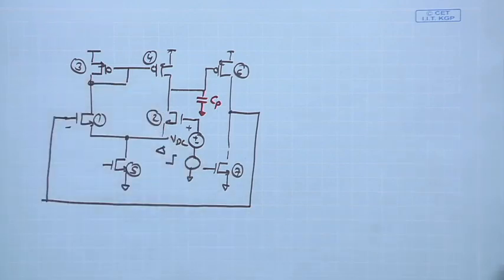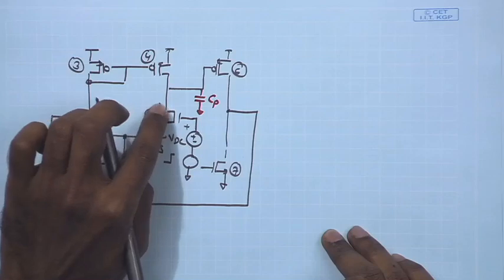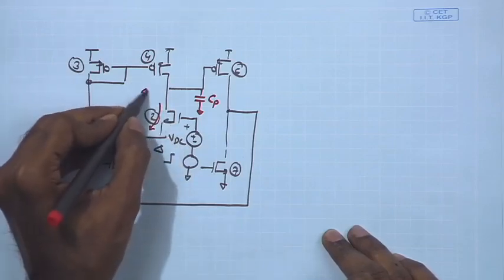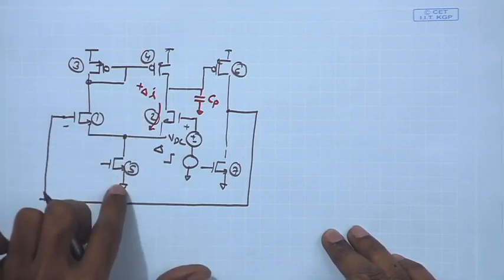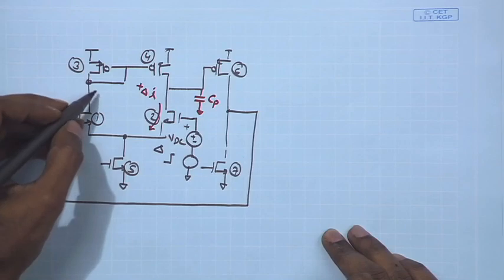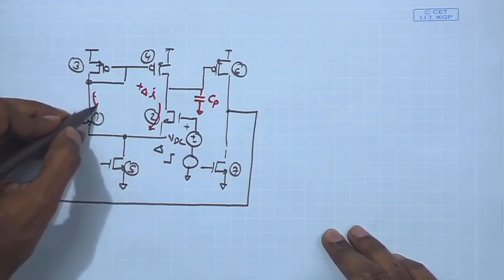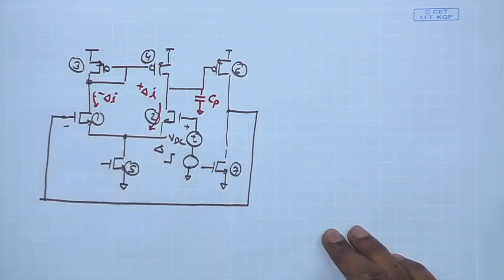Therefore, of course, we know the differential amplifier operation will increase the current in say M2 by delta I, and since the total current is constant, provided by this M5, there will be a reduction in the current going in M1. So, here you will have minus delta I, the same amount. So, that plus minus, the total current remains the same.